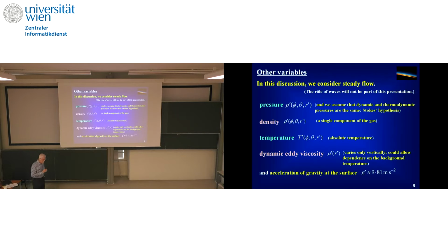Okay, of course, we've got other variables to worry about. We've got the pressure, and I'm going to invoke Stokes' hypothesis, i.e. dynamic and thermodynamic pressures are the same. As I've already commented, we'll have a single component of gas, and that's its density. We'll have a temperature, of course. We have the eddy viscosity and acceleration of gravity at the surface.